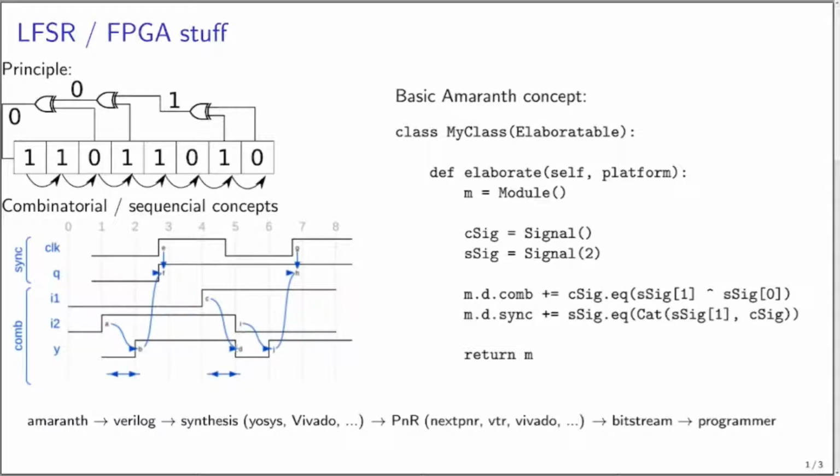Here the output of the XOR changes 2 times, but the output of the sequential part is not updated until the next clock edge. In fact, here we don't show a change in the Q signal, but it's due to the fact the output of the XOR is again high.